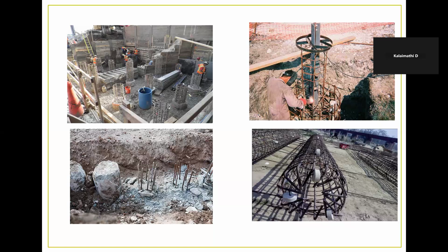Construction methods used for sheet piles are anchored sheet pile and cantilever sheet pile. And construction methods are divided into two categories. One is backfilled structure, another one is dredged structure. The sequence for the backfilled structure is initially the soil in situ is dredged in front, and then backfill is proposed. Then the sheet piles are driven, and then the anchor system is backfilled up to the level where we have to place the ground level.